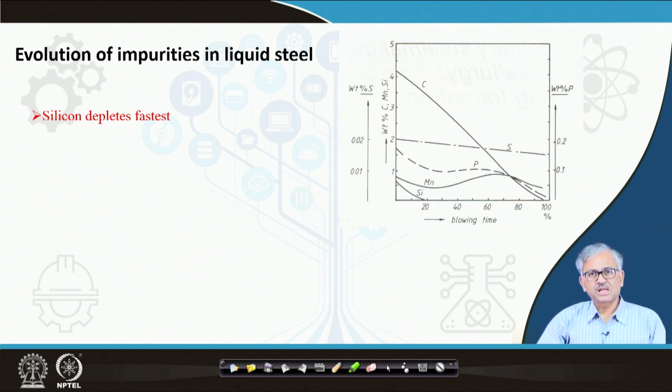So when the basic slag forms, the manganese oxide does not become comfortable in the slag because it feels repulsion. In thermodynamic words, its activity coefficient increases. For the same concentration of manganese in the slag, when the basicity increases, its activity coefficient increases. As a result, its activity increases at the same concentration level.